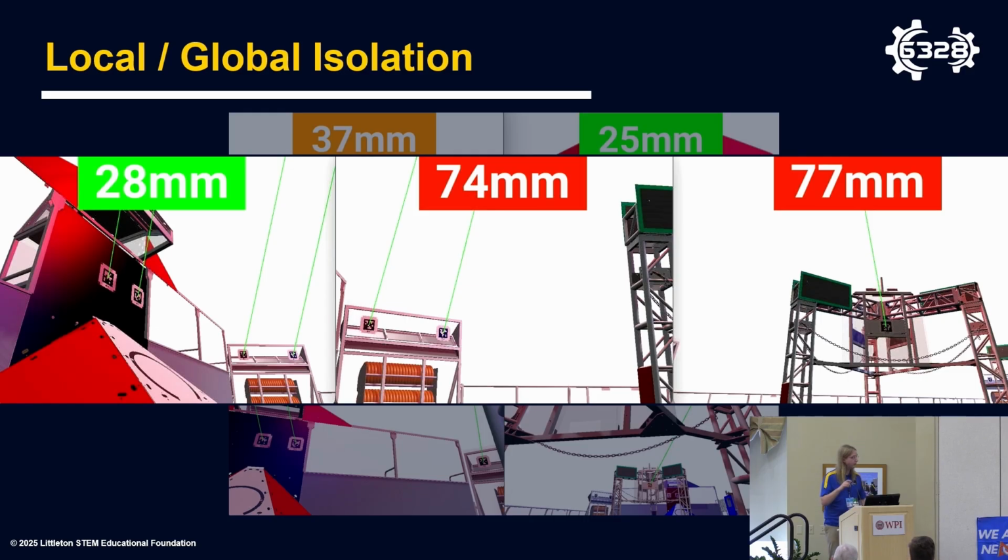I also want to note that in all of those cases, when we're shifting between different pose estimates, we're always using the same coordinate system. We're always using this field coordinate system. The difference is that it's changing so that our robot pose is correct relative to different theoretical field elements. So we can measure relative to the theoretical location of the amp and know that we're correct relative to the amp in reality. Now, this is something we did really successfully in 2023.